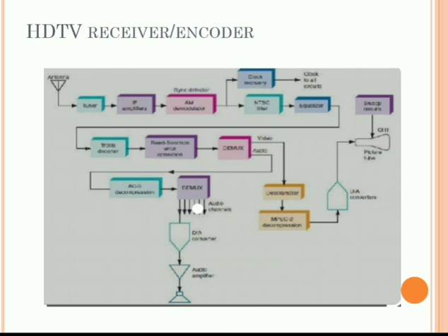What is scrambling? It is to suppress the synchronization signals at the transmitting end. A picture without H and V synchronization cannot lock into a steady picture and is seen as rolling pictures and diamond bars. For descrambling, a pilot carrier containing the synchronous timing information is transmitted on a separate carrier.